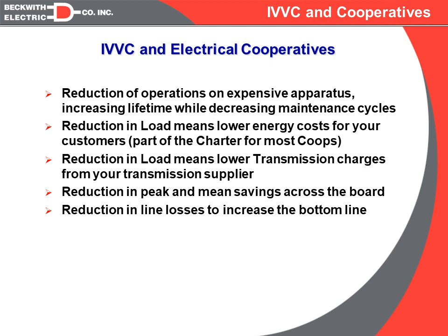Also, if your charges from the investor-owned or your energy provider are off of peaks, by shaving the peak, we can reduce your overall load or your overall bill. And finally, by reducing our losses by having the capacitor banks, we can increase the availability of your overall system so that you can get more real power through that system to your end consumers.